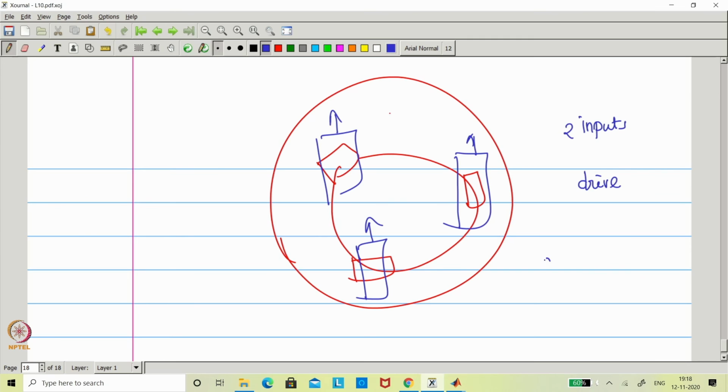That is what we call synchro. It is synchronized. So, synchro drive. A synchro drive will come with a minimum of 3 wheels; it can even go to 4, 5, 6 and so on. But this is one special case for which I cannot derive the model straight away, because it has two things. One is the drive, and the other is the synchro drive, which tries to synchronize all three. And if you look at it, the same motor is used for both. That is the speciality of the synchro drive mobile robot.